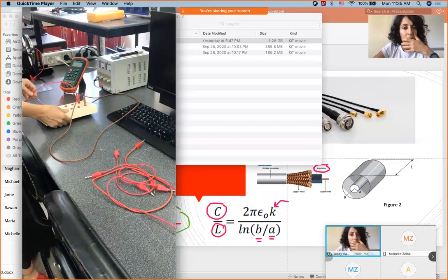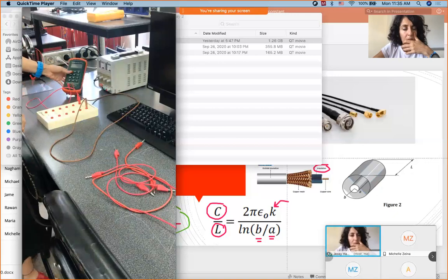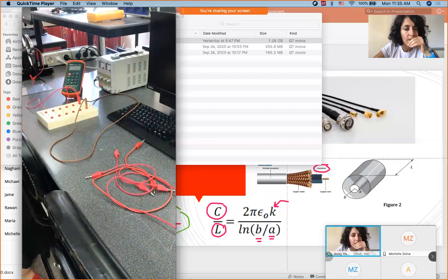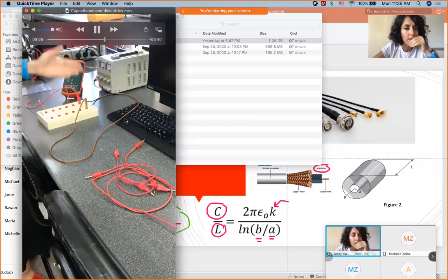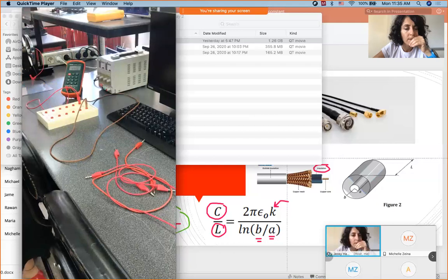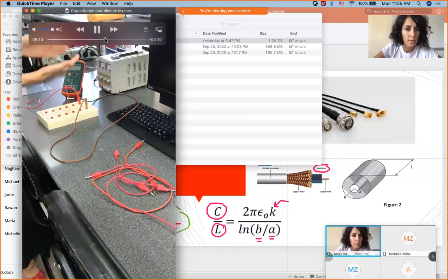I just wanted to be able to compare, which means I expect my LCR meter to change its unit automatically to nano or microfarad. It gives me 470.6 nanofarad, or something that could be 0.47 microfarad. This is called the measured value, and what's written on this one is called the nominal value. Nominal is what's written on it.